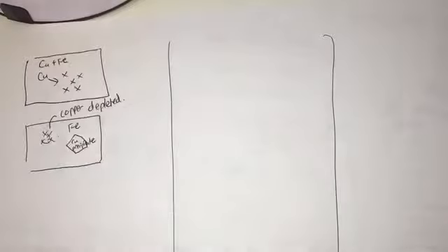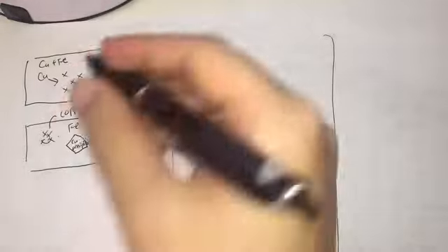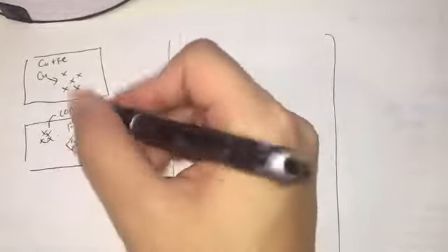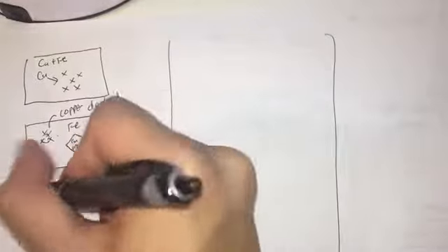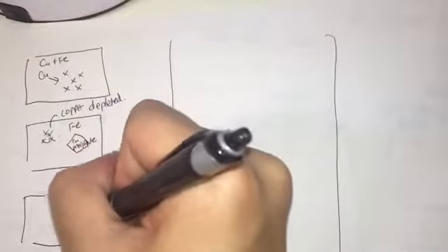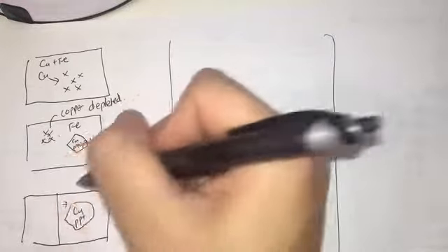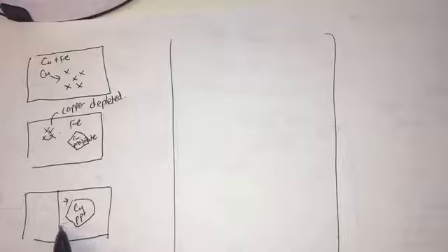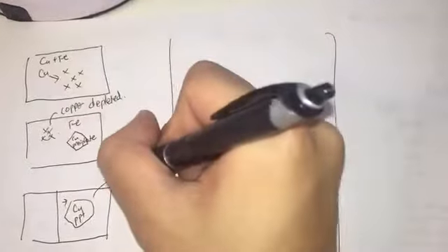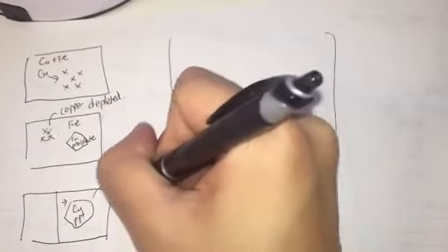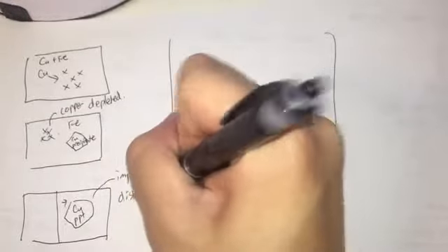Now what happens if we have precipitates in the reactor pressure vessel steels? Think about how these dislocations will move when they meet this precipitate. If I have a copper precipitate, and this dislocation is moving this direction, it will see the copper precipitate, and then it will require more energy to move past it. So this actually impedes this dislocation motion.